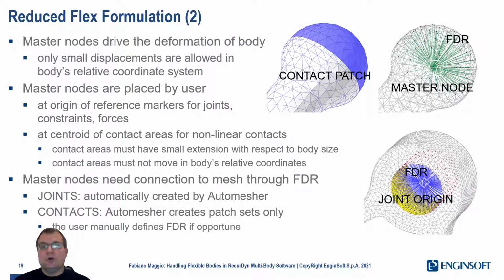The master nodes will be used to make joints, forces, and constraints, but the effect of that constraint will be distributed over a number of nodes.